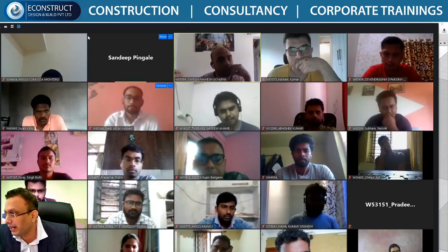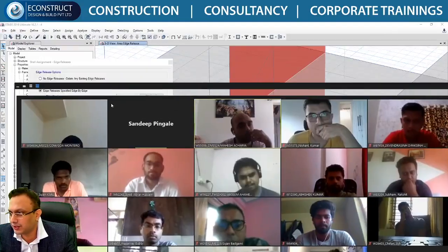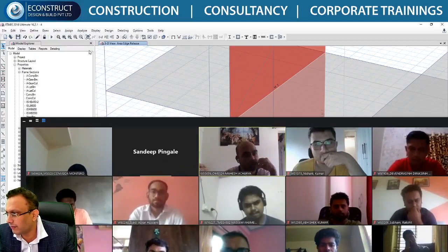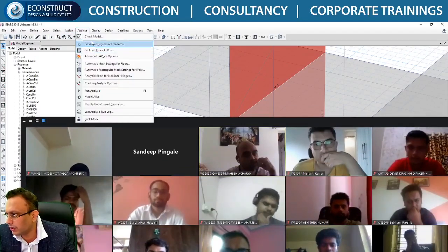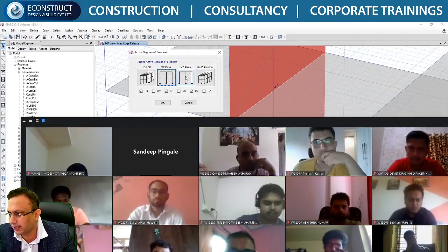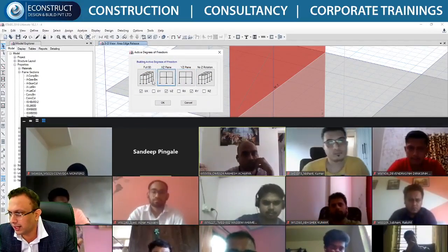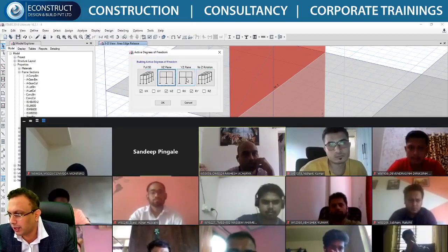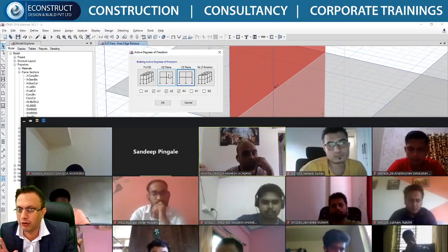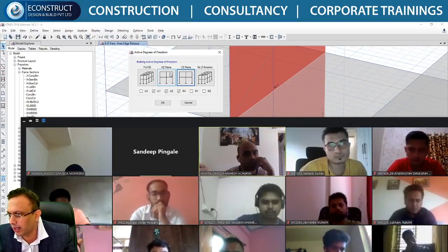Yeah, probably you might have given the space frame in that case. See, first thing is, in yesterday's module we gave one truss. So you go here, and here you need to give XZ or YZ plane. If you forget this and go to the space frame, then it will give you the instability warning. But if you go to the XZ or YZ plane, it won't give you. Just check it out. Even after giving this, if it is giving you a warning, then you can show me the model. I'll just look into it.